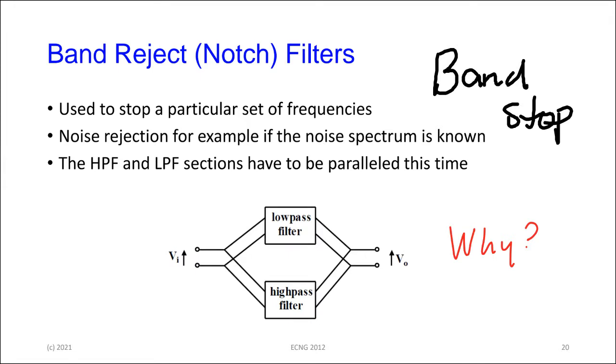There's a lot of 60 hertz background noise. And if you're doing precise measurements of signals, and you're not careful about it, that 60 hertz signal is inbuilt to the signal that you're trying to measure in the first place.